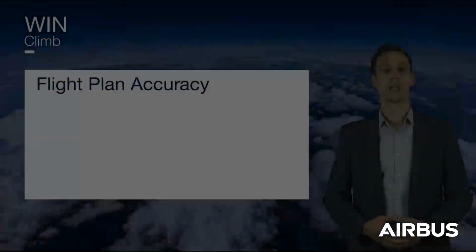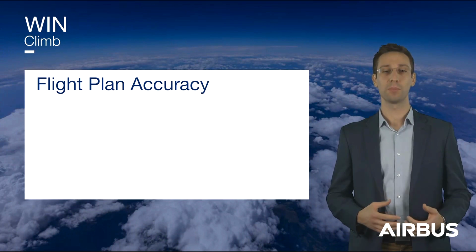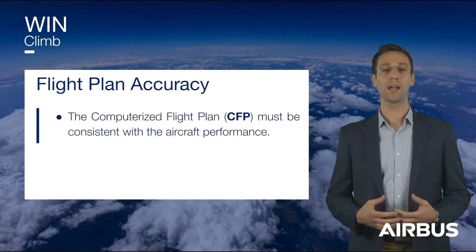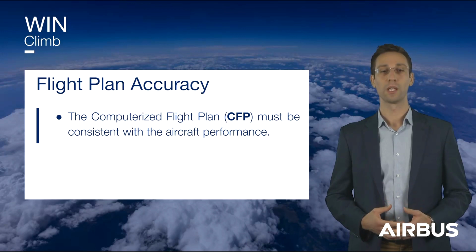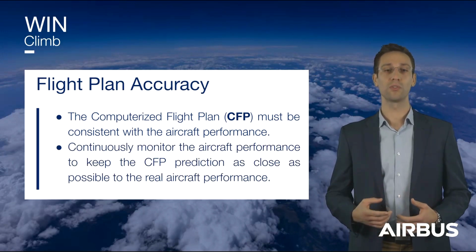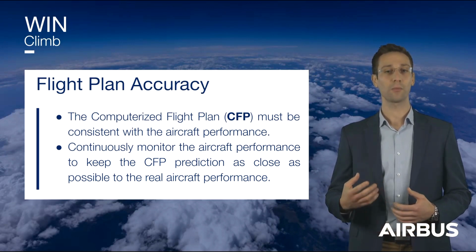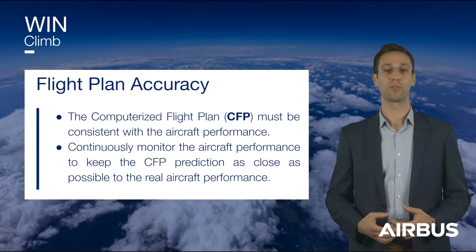As you are aware, in terms of aircraft operations, an accurate computerized flight plan is one of the most important ways of reducing fuel burn and CO2 emissions. However, the nature of some of the parameters can result in some lack of accuracy. In order to make the best of the CFP, it must be accurate and in line with the aircraft performance. It is then important to continuously monitor the aircraft performance to keep the CFP prediction as close as possible to the real aircraft performance.